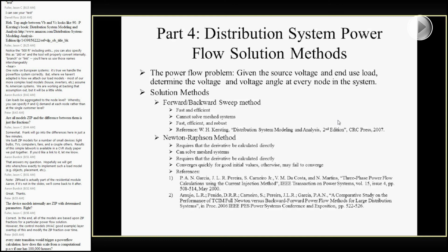So for example, right now we use what we call a minimum time step, and you'll see these a lot in some of our studies. Basically, we can set a global variable called minimum time step, and we'll set it to say 60 seconds. What that does is it basically decouples the solution for 60 seconds. All of the individual objects still update their own internal states, but they don't check with everybody else to see if they need to update the information shared across the objects. So it does introduce a certain level of uncertainty into the problem, and it's a trade-off of speed versus accuracy.